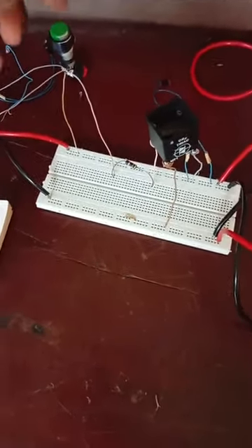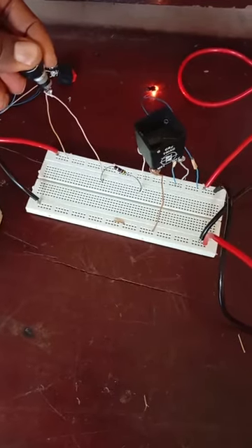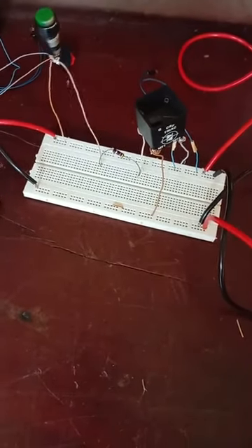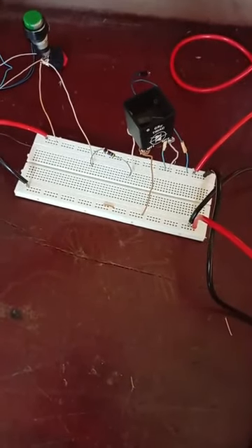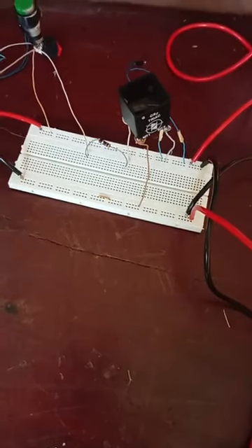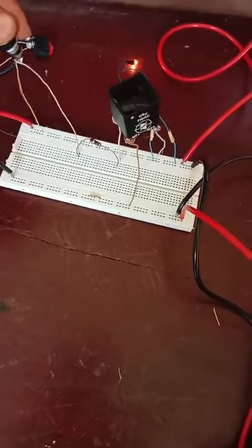But why must we hold the switch? Why must we hold it before we are going to have our load? Because a Triac cannot control an AC source without a triggering voltage from the gate. It's the gate that will trigger it to operate.